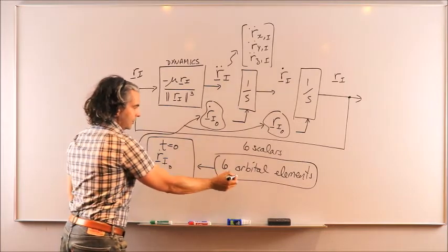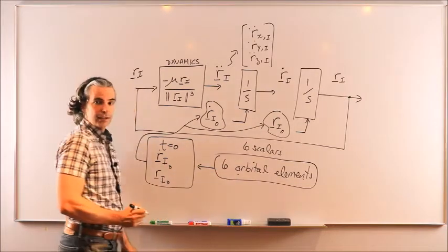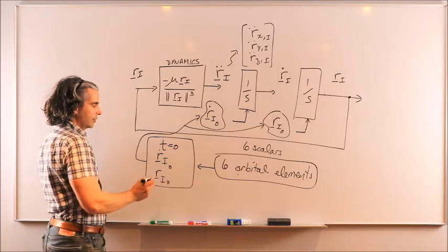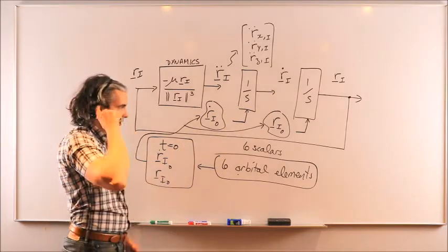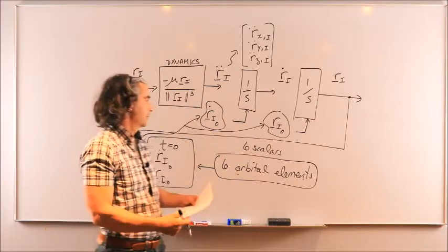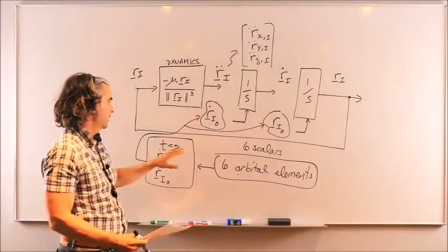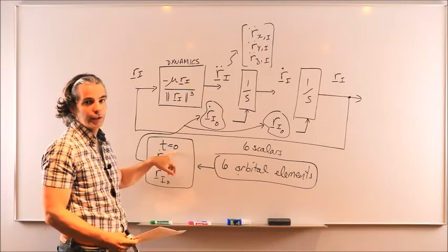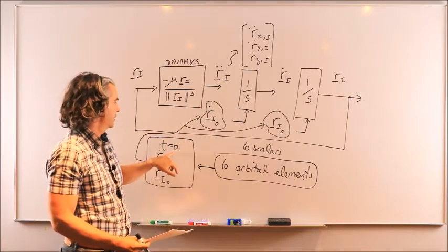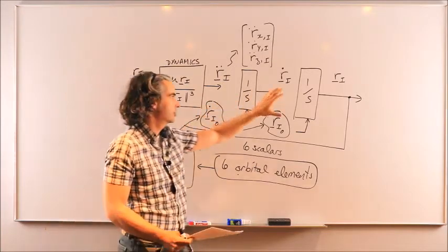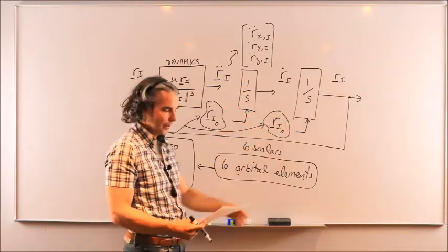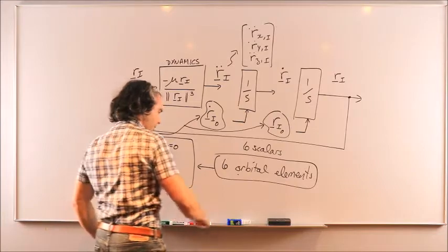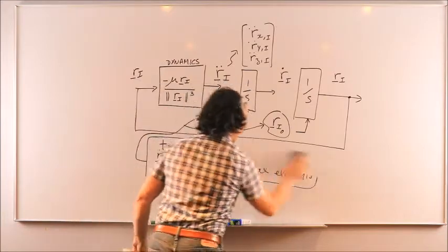So first, we're going to have a look at the 6 classical orbital elements that we're going to use, and then the process to turn them into position and velocity at some arbitrary time. For this process, just keep in mind that that specific time will be t equals 0 seconds, because those are used as initial conditions, or as conditions at t equals 0. Okay? So that's going to be the bulk of today's work.